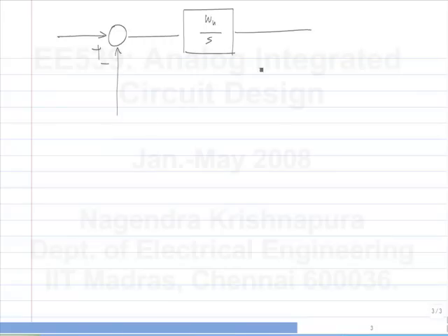And we also along the way saw the importance of loop gain. If the loop gain is frequency dependent, where it is large, you get a nearly ideal response, and where it's small, you get quite a non-ideal response. So the point where the loop gain crosses unity is a kind of breaking point between the ideal response and the non-ideal response. And as far as the DC loop gain is concerned, that determines the relative accuracy. The relative accuracy of the DC gain of the closed loop system is the inverse of the loop gain.